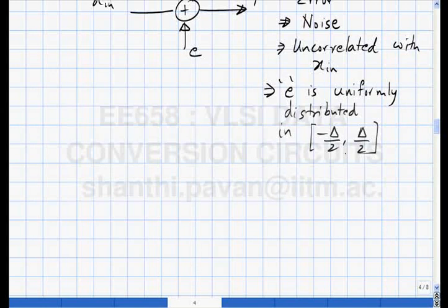So the next question is, once you have noise, you have to define its distribution function. You just say it's uniform between minus delta by 2 and delta by 2 because it's a constant, it's easy to integrate, differentiate, all sorts of nice stuff. And then we assume that we're all right and carry on with life. It's amazing that using such completely bogus assumptions anything works at all. But it turns out that it does.